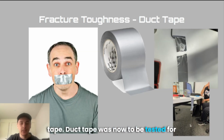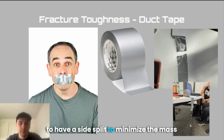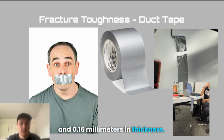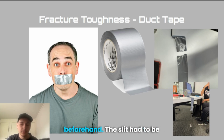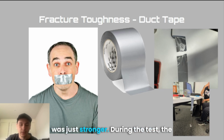Duct tape was now to be tested for its fracture toughness. We again decided to have a side slit to minimize the mass needed. The duct tape had dimensions of 46.85 mm in width and 0.16 mm in thickness. Also, the width of the slit was 28.61 mm, which was quite more substantial than the other tapes beforehand. The slit had to be quite a bit larger as duct tape overall was just stronger.